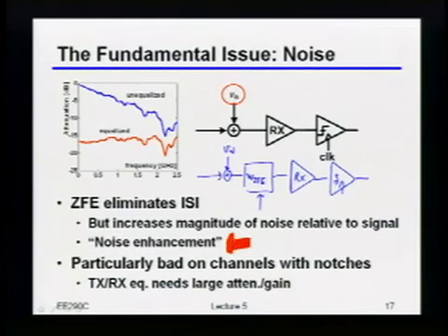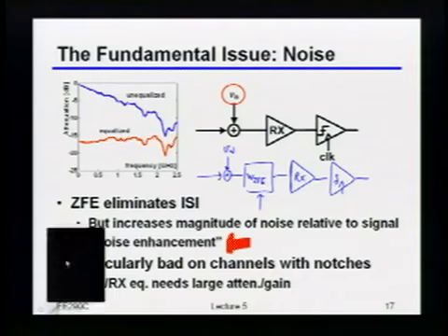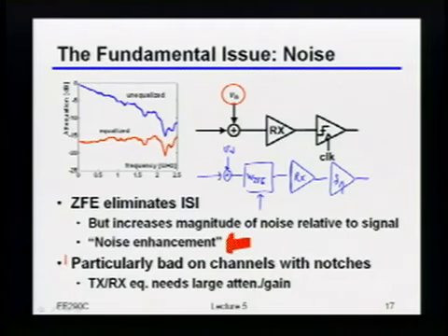But it's completely equivalent. Are we making some assumptions about where the noise is coming from? Okay, so good. So you guys are circuits guys, so that's good. Usually when you talk to the comm people, they just sort of assume this is the fundamental thermal noise that's out there in the world of you transmitting a wireless signal. Which, by the way, even here exists, because you've got a 50 ohm term at the end of your line, right? And that has some fundamental noise in it. So you're absolutely right that when you really build this, that's going to have its own noise contribution.